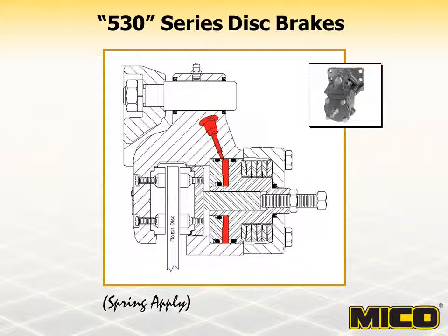This brake is designed for use with a rotor disc thickness of 5/16 to 1/2 inch and a disc diameter of 9 inches to unlimited. Properly adjusted, this brake provides maximum brake torque when no hydraulic pressure is present. It is not self-adjusting, so regularly scheduled manual adjustment is required to compensate for lining wear.